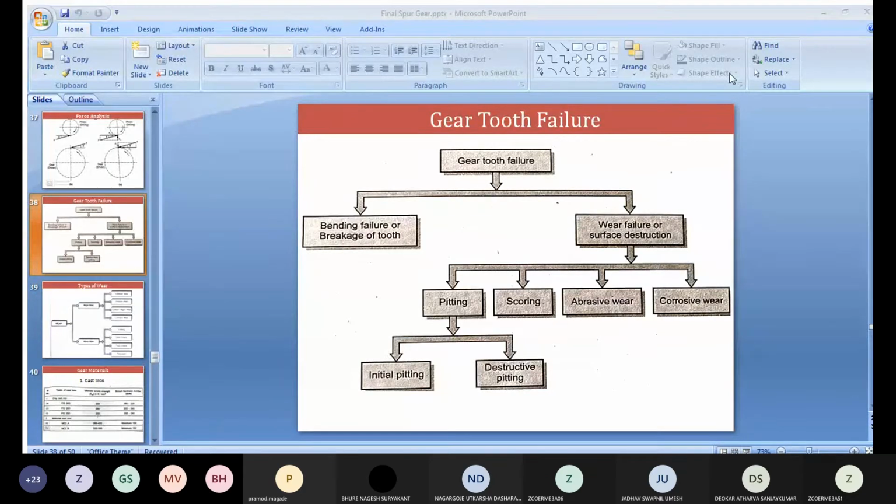Correct. So again, for the solution to this, we'll have to use a highly viscous lubricant so that these kinds of weld spatters, dust, dirt particles can be removed by using lubrication. Clear? So that's why, if we are using this lubricant properly with proper viscosity, we can avoid two types of failure, like scoring and abrasion. Last, corrosive wear, corrosion.